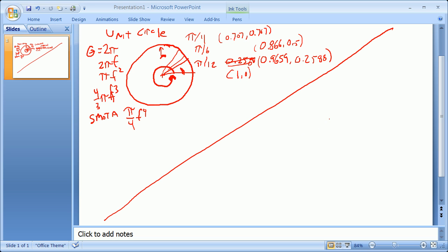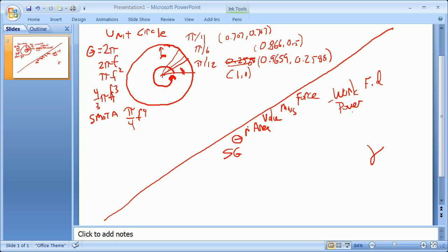Next one, of course, was the circle of units, and we'll just talk with the concepts here going around, starting with specific gravity on one leg and unit weight on the other, and of course force up on top. Along with specific gravity in the unitless category is angular displacement, which is radians. Then we have distance, we have area, we have volume, and we have mass. From force we go to work, which is F dot D. We have power, which is work over time. We have pressure, which is force over area, or work or energy over volume. We have torque, which is R cross F, and then we have mass density.